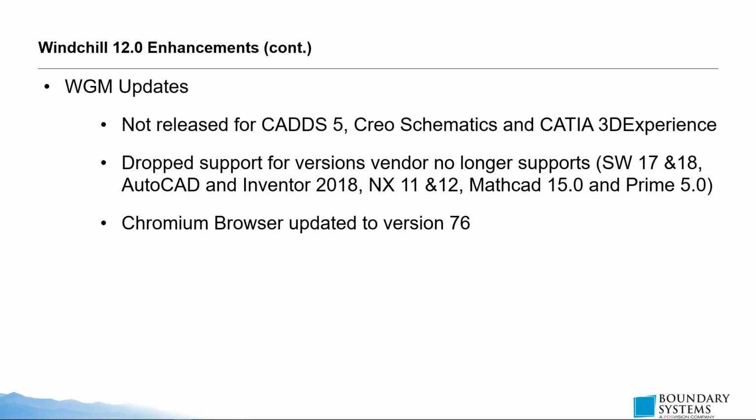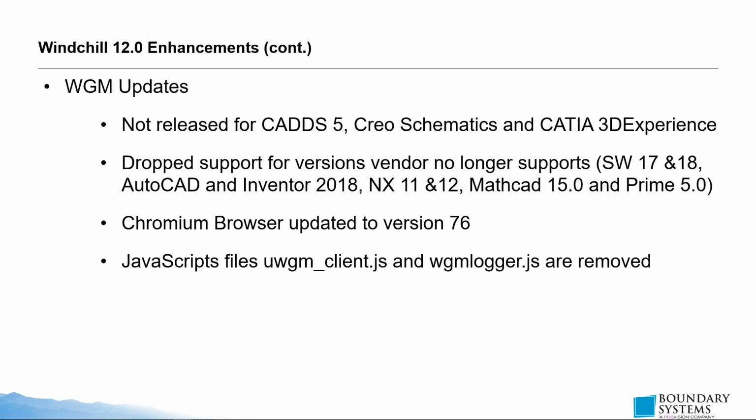Also, Chromium browser update. So the embedded Chromium browser has been updated to the latest version, version 76. And then also JavaScripts. If you use the UWGM client JavaScript or the WGM logger JavaScript, those have been removed. So what you will need to do is basically transfer any applications, any startups, anything that you had associated with those need to be reconfigured because moving forward, those will not be available.